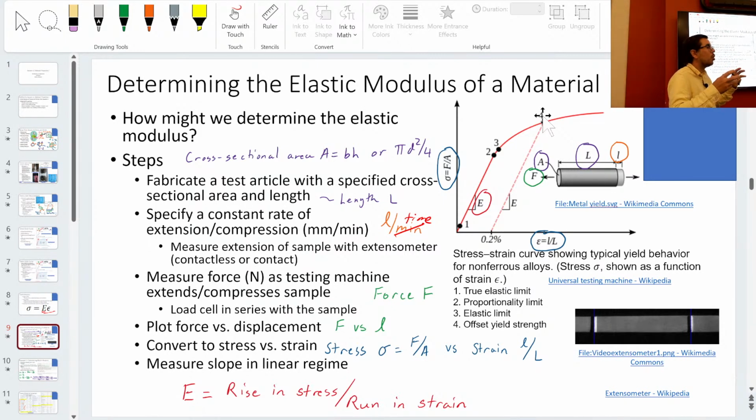surface stronger. And you're like, wait a second, who cares? Why don't I want the inside to be stronger? I want the whole piece to be stronger. Well, yes, often we do, okay? When we look at, not so much in tensile testing, but when we look at shear, shafts, twisting, right? We talked about shafts already. When we look at bending, beams, it turns out the highest stresses are usually at the outside.